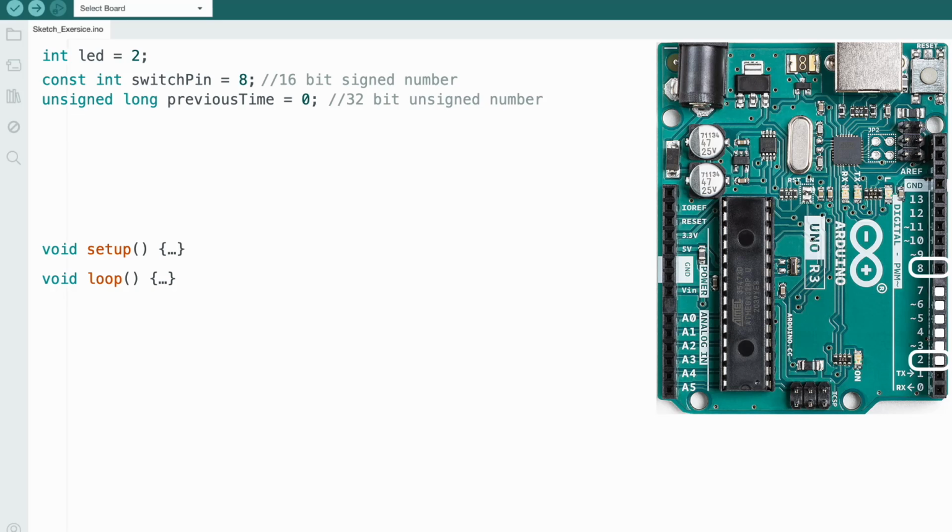And so with this program, that's why we're looking at the difference between signed and unsigned, because we do quite a bit with time here, and we'll see more of that later on as we progress through the code. So here we have our switch state and our previous switch state, and when we look at the tilt sensor, all we're trying to do is figure out if the last time that we read in from our tilt sensor, if the angle was different than it currently is. And this is how we know if the board is being moved or twisted or tilted or whatever it is.